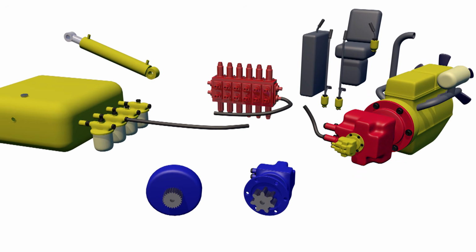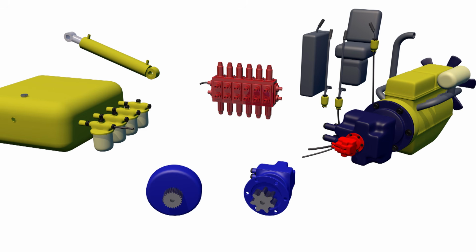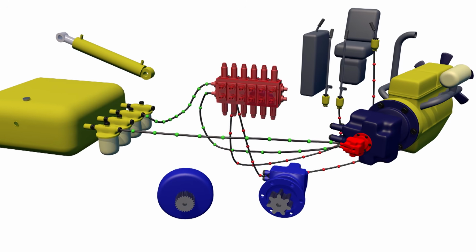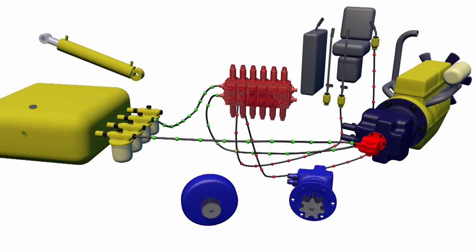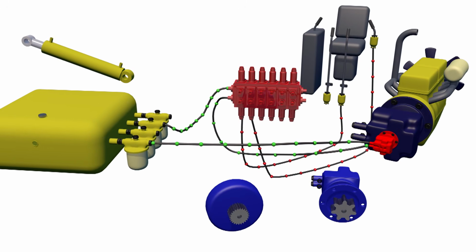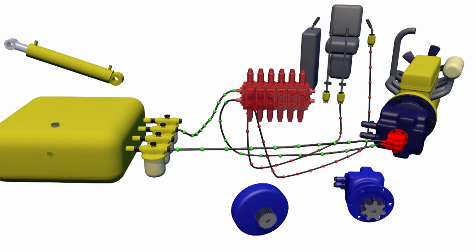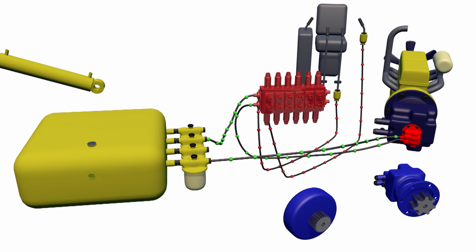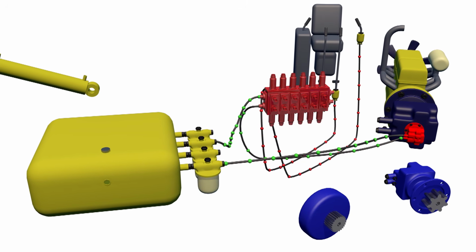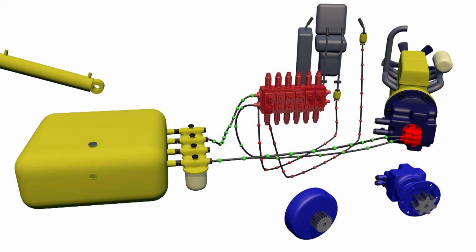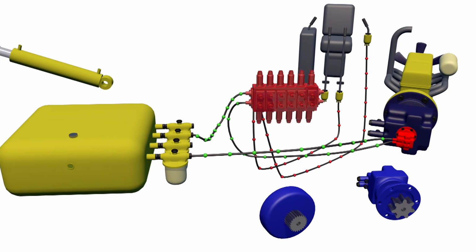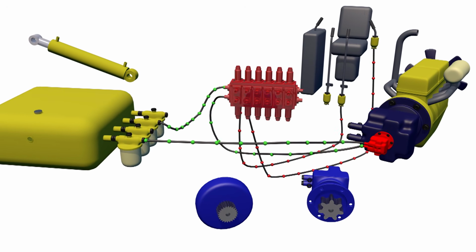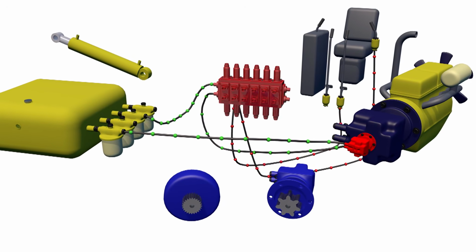The pilot circuit of a hydraulic excavator is an auxiliary hydraulic system. It uses low-pressure oil to remotely control the heavy main spool valves of the distributor. This ensures smooth and precise control of the machine without requiring physical effort from the operator. It is usually integrated into the main pump unit. It generates a stable but low flow of oil at low pressure. The pilot oil lines to the joysticks are shown in red. Joysticks and pedals control units are located in the cab. When the lever is moved, they open internal valves, metering the flow of pilot oil.